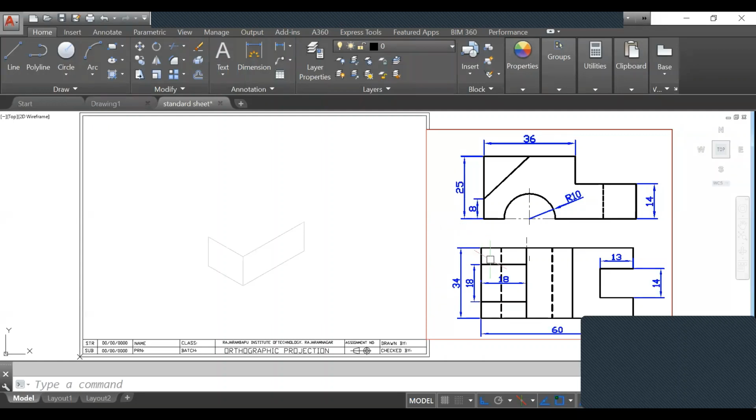Let us consider this side, this corner and this corner should be on this line, particularly, or this part. Here it is the origin point. Okay, so this O should be matched with this one. If I capture this front view and place it on this surface, then this O should be matched here. But if I capture this front view and place it here, in this region, this O would be on this side. This corner would be on this side. So that will not match. Getting? So that's why the front view should be on this direction, not in this direction. Front view should be on this direction only. Okay, so that's why you will get the left hand side view here. So here it is 34.